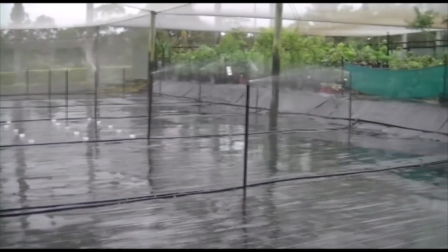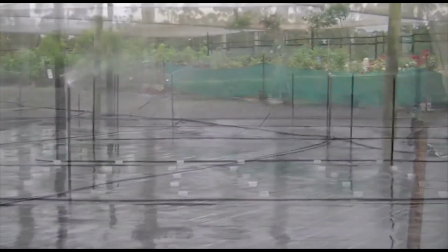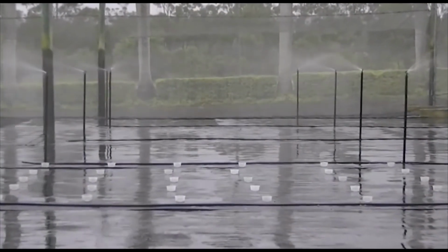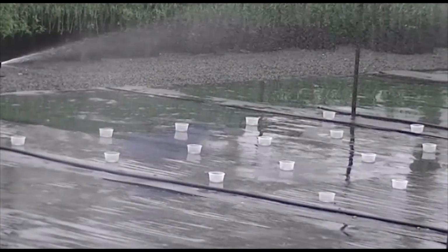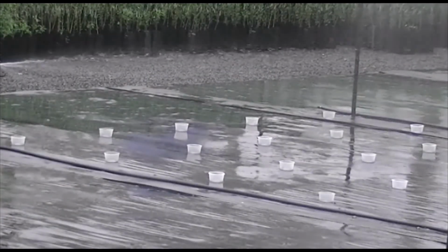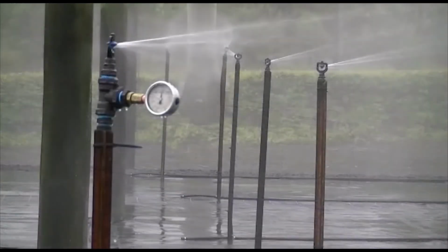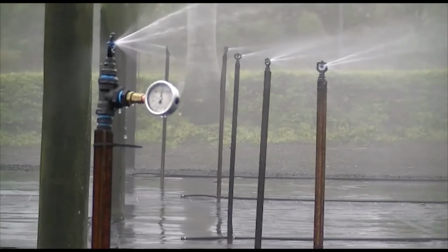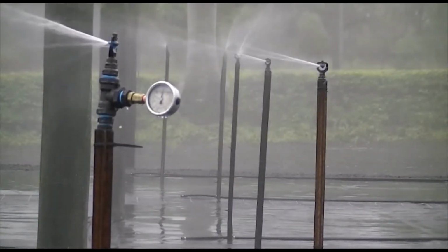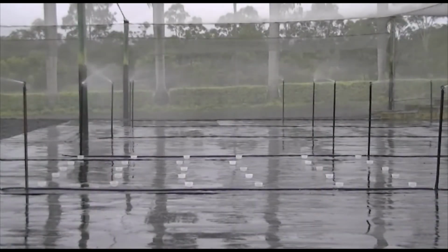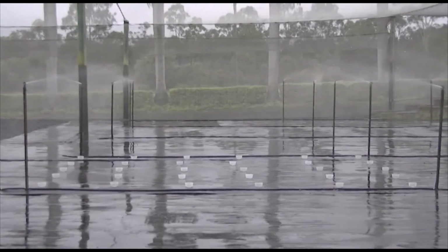The layout of an overhead sprinkler irrigation system should be set out to industry best practice. To achieve best practice and obtain scheduling coefficients of less than 1.5, sprinklers should be arranged to ensure every container in an irrigation zone or grid receives water from 4 sprinklers. Older conventional system designs do not provide this sprinkler layout and deliver much higher scheduling coefficients, causing excess water use, increased watering time, nutrient leaching, uneven cropping, increased labour costs, and reduced production.